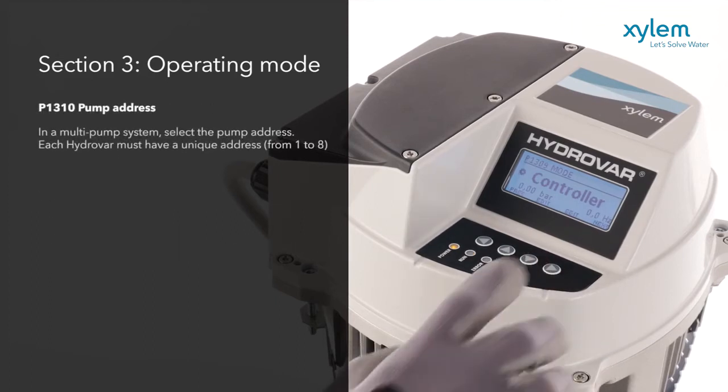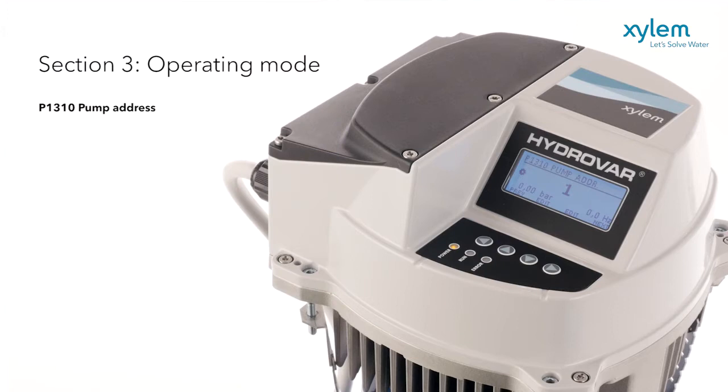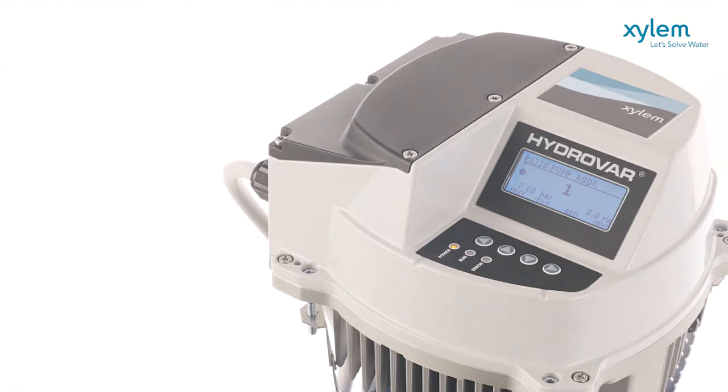In multiple pump systems, Hydrovar allows up to 8 pumps to be connected via the RS485 interface, making each pump totally independent if a failure occurs to either another pump, Hydrovar, or sensor transducer. Note that a screened cable is required along with a unique pump address for each pump.